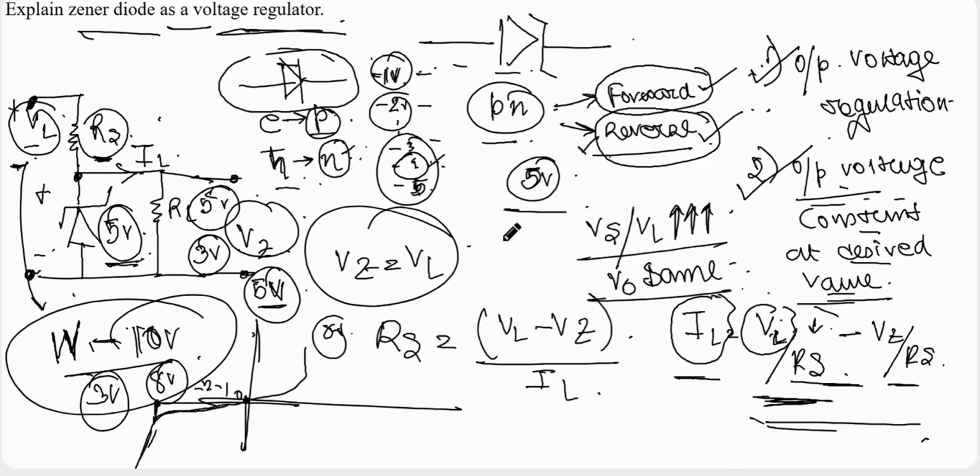Okay. So the input voltage varies from 0 volt to any value, up to 15 volts, 1, 2, 3, 4, 5, 6, from any value, the output voltage will remain the same. It cannot exceed this breakdown voltage. The zener diode always limits the output voltage to 5 volt.